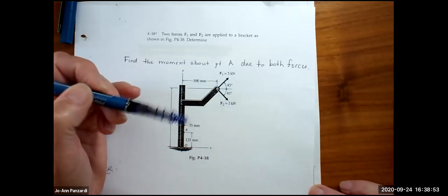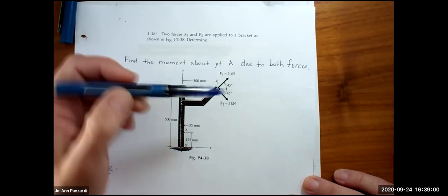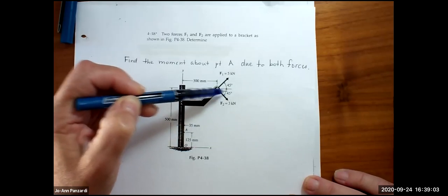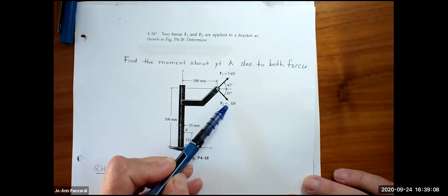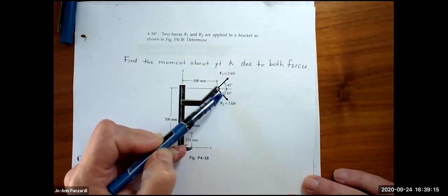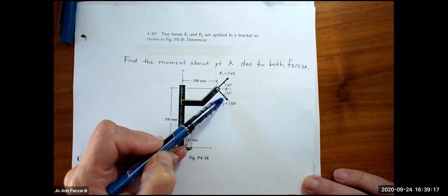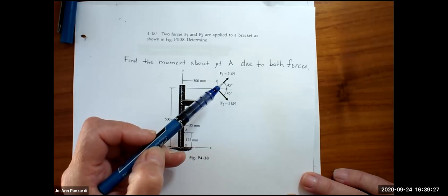You know, when I'm doing grading, I'm still looking at your free body diagrams because those are so important in statics. And sometimes you guys are still leaving out the direction of the force. Everyone's showing the arrow. Everybody's writing the variable or the numerical value of the force, but many times you're leaving out the direction, which either can be written in an angle form or in distances. Particularly with the 3D problems, don't get sloppy. Those 3D problems just take a long time to draw, and you've got to draw them clearer.